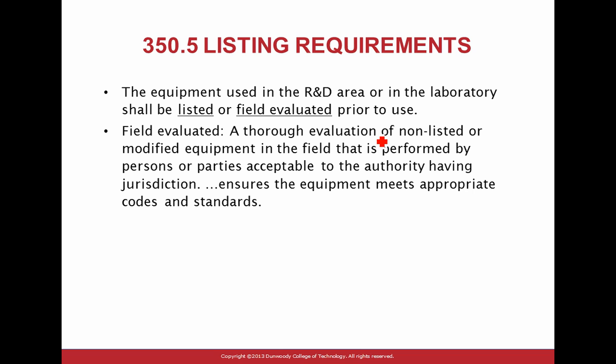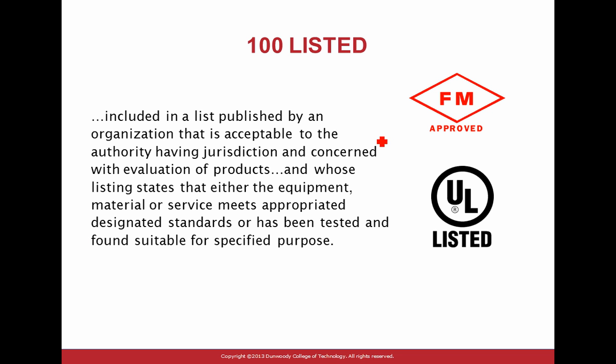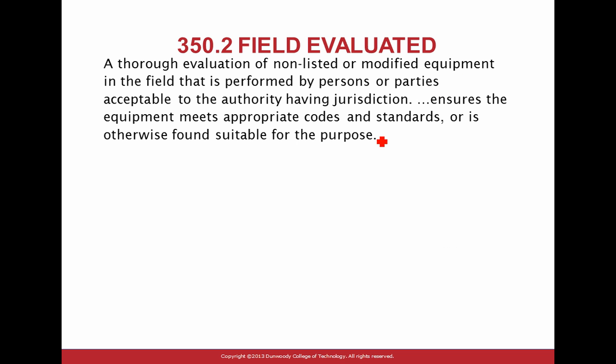Field evaluation: all the evaluation of non-listed equipment. If it's not listed, came from China, it has to be field evaluated before it's installed. We talked about listing. I don't know if you use Factory Mutual FM. I'm sure you use a lot of UL listed equipment, right? Everybody has to. Field evaluation: a bunch of smart engineers, Chad is not one of them, can come to your facility, evaluate the equipment, and give you an equivalent listing.